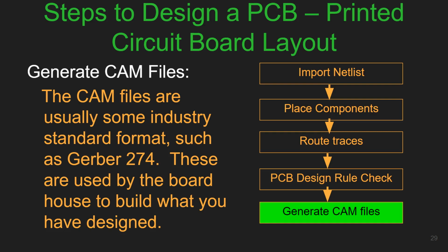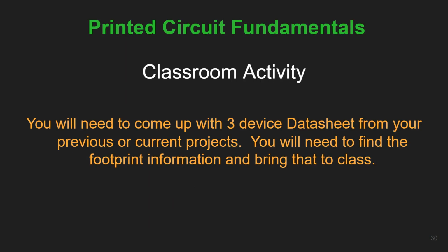The standard format used for CAM files is Gerber 274, and we might be using Gerber files in KiCad. And to read about the PCB design rules, you can refer to the reference slide at the back of this PPT.